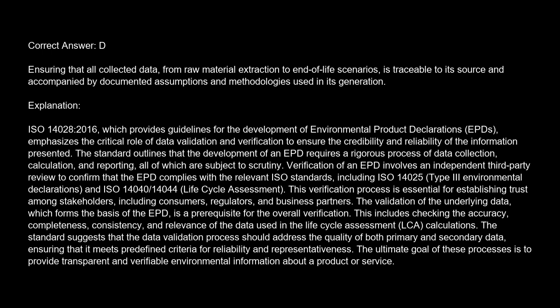The validation of the underlying data, which forms the basis of the EPD, is a prerequisite for the overall verification. This includes checking the accuracy, completeness, consistency, and relevance of the data used in the life cycle assessment, LCA, calculations. The standard suggests that the data validation process should address the quality of both primary and secondary data, ensuring that it meets predefined criteria for reliability and representativeness. The ultimate goal of these processes is to provide transparent and verifiable environmental information about a product or service.